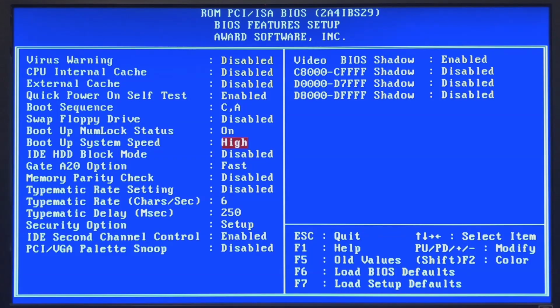By the way, the deturbo function does not actually halve the bus frequency here. According to the datasheet of the chipset, this just idles the bus periodically, and that is probably for 2/3 of the time. However, I don't know. I did a lot of measurements and most of the benchmarks and tests performed exactly at the 50% mark. So in the end, I don't think the very fine technical details matter. Based on performance alone, we can just think of this as halving the bus speed, and just keep in mind that this is not that consistent.